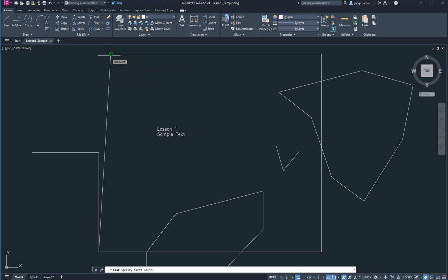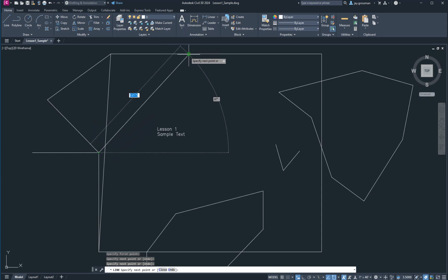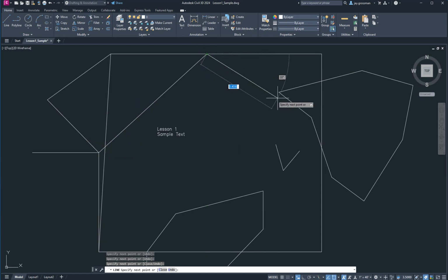That means I'm snapping to that point. So I'm going to be right exactly on top of that point. And now if I hover over here, it snaps right to it. If it's got that little hourglass shape, that means I'm snapping on the line to the nearest point to it. Over here, if that box shows up, I'm snapping to an endpoint, and it tells you what you're snapping to. Right, through that. So I'm able to snap on that.